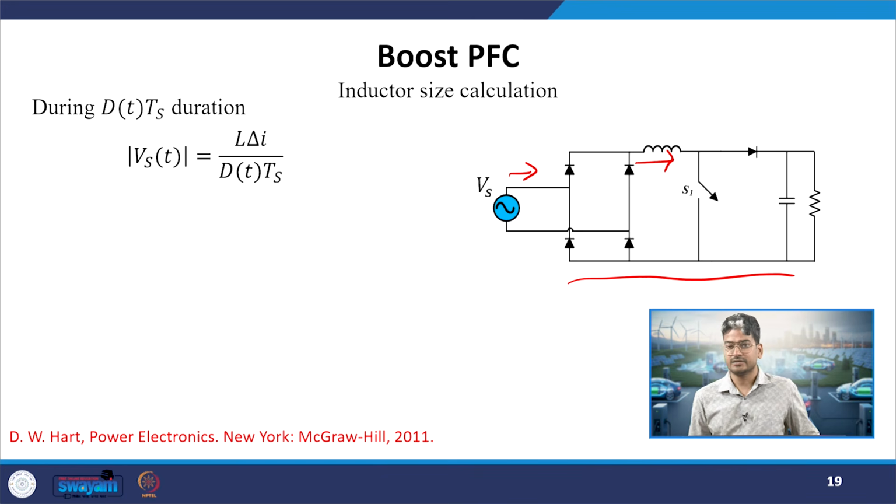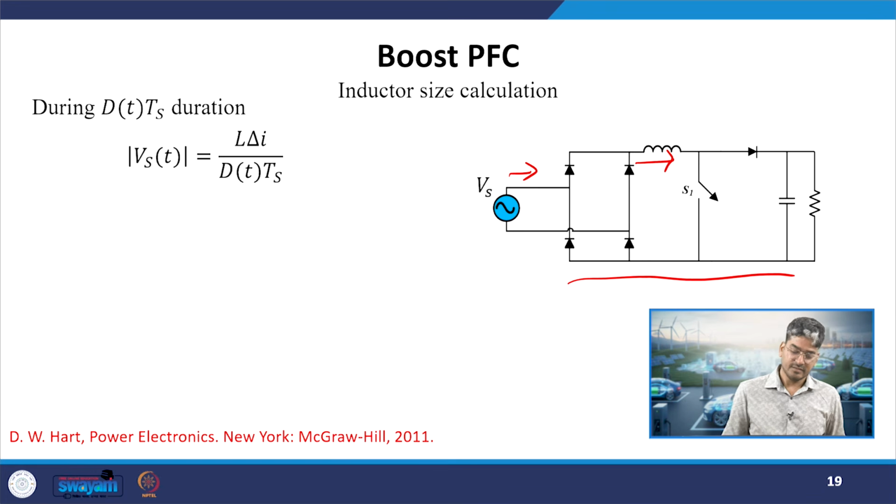On the output stage we have a capacitor, or for our charging application, if instead of a capacitor we have a battery bank, we will have a similar type of observation. The current will become peaky and the power factor will be very poor. So, we will have a power factor correction circuit in between. The first example which we have considered over here is our Boost PFC.